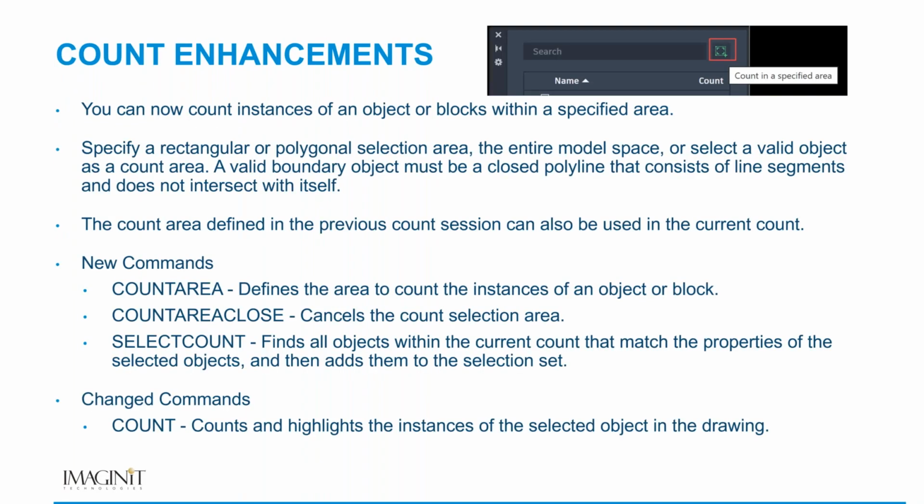The default layer being used for trace: there is no default layer. The trace exists outside of layers. Think of trace as onion skin. For those of us that have been around for a number of years, think of it as an onion skin that you would put on top of a paper drawing.